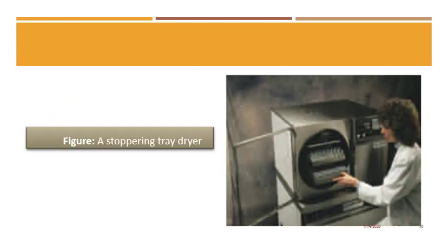Class, here you have a stoppering tray dryer, in which the trays supply the heat needed to remove moisture, and after completion of lyophilization, which means about 24 hours, the device automatically stoppers all the vials that we placed in it.